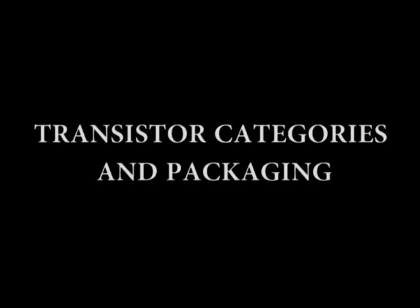Transistor categories and packaging. BJTs are available in a wide range of package types for various applications. Those with mounting studs or heat sinks are usually power transistors. Low power and medium power transistors are usually found in smaller metal or plastic cases. Still another package classification is for high frequency devices. You should be familiar with common transistor packages and be able to identify the emitter, base and collector terminals.